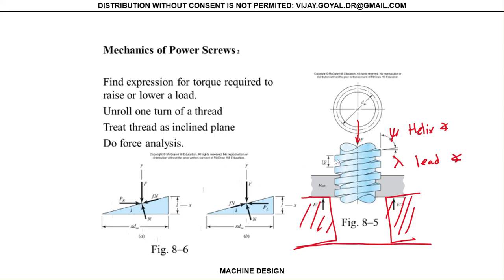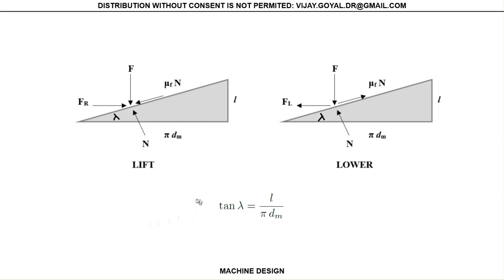So this analysis here is thinking, let's take one piece right here and see what happens. Your pitch angle goes from one edge to another edge. You can do the crest, but crest is only good when it's actually pointed, right? When it's squared or ACME series, then you have to go from one edge to another. That's your pitch angle. And all the threads are going to have exactly the same pitch angles as well.